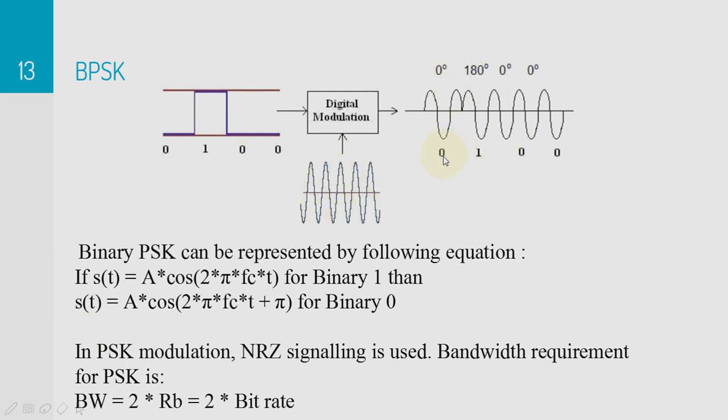To overcome the drawback, BFSK, two-level binary FSK, or multiple FSK modulation techniques with more than two frequencies have been developed, like 4 FSK, 8 FSK. So different frequencies can be available. In MFSK, that is multiple FSK, more than one bit is represented by each signal element.